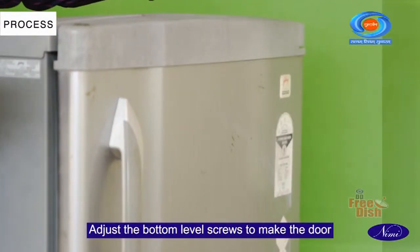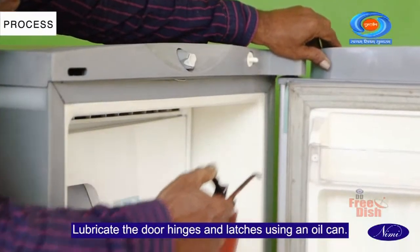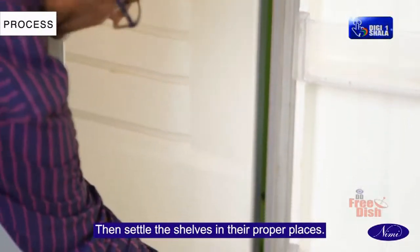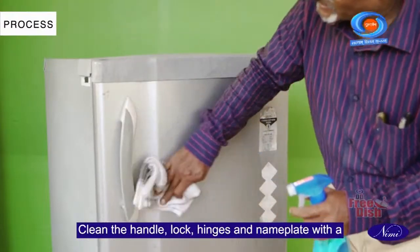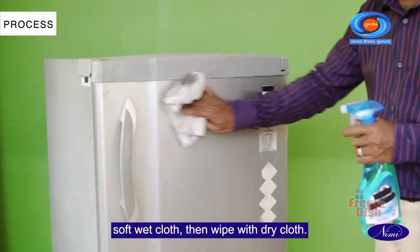Adjust the bottom level screws to make the door close automatically in balance when closed slowly. Lubricate the door hinges and latches using an oil can. Then, settle the shelves in their proper places. Clean the handle, lock, hinges and nameplate with a soft wet cloth, then wipe with a dry cloth.